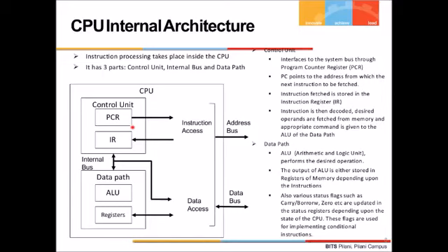So once the instruction is fetched, it is stored in another register called the instruction register. And then from the instruction register, the instruction is decoded. Okay, so for example, add ax comma bx. This is an x86 instruction. So this has to be interpreted in the language of the ALU, right? What to do. So that's why there is something called the instruction decoder, which will take the instruction from the instruction register and decode it and feed it to the ALU, like the data path.